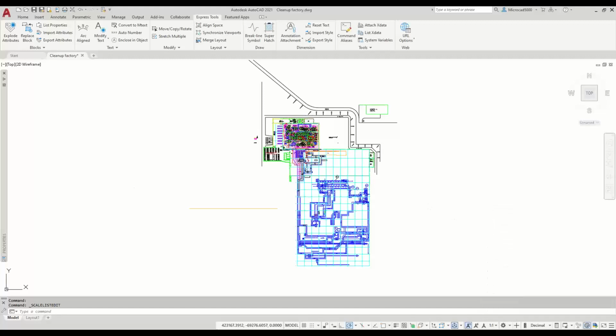Yeah, quick and simple as that. And that is set for this drawing file forever and a day. The question is, why did it cause that? Well, there are some settings in the background that will make AutoCAD use imperial settings. Even though you started with a metric template, if that metric template wasn't set up correctly, you can still have hidden imperial settings.